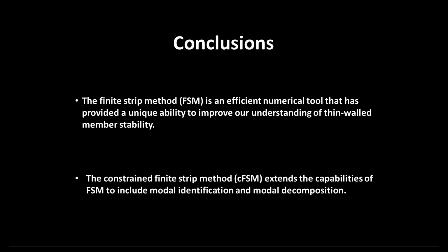From conclusions, what we learned: the finite strip method is an efficient numerical tool that has provided a unique ability to improve our understanding of thin-walled member stability. The constrained finite strip method extends the compatibility of the finite strip method to include modal identification and modal decomposition.